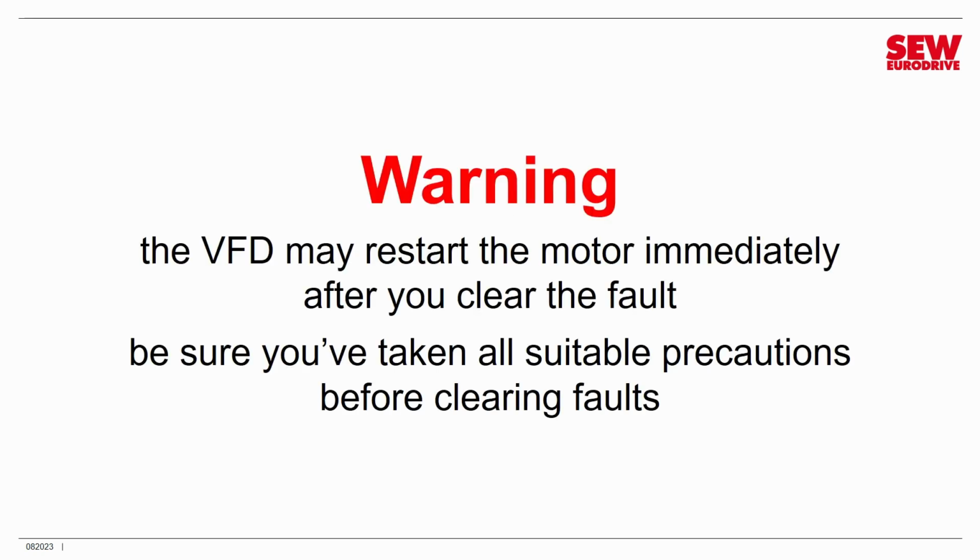Now let's pause for a second. I want to give you a warning. The VFD may actually restart the motor immediately after you clear the fault. It depends what it was doing when it faulted and what state the controls are in. Therefore, you should always be absolutely sure you've taken suitable precautions before clearing faults, that you've considered the possibility that the motor may restart. If you don't want that to happen, be sure you've removed the enable on the VFD or done something else to immobilize the drive. Okay, you have been warned.